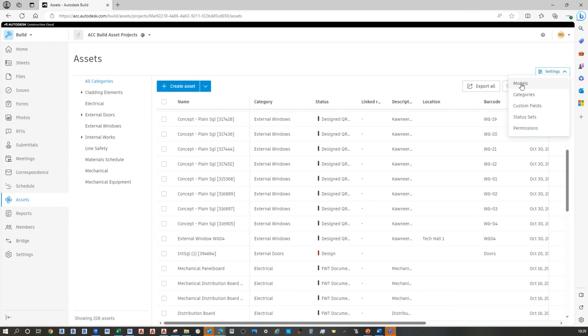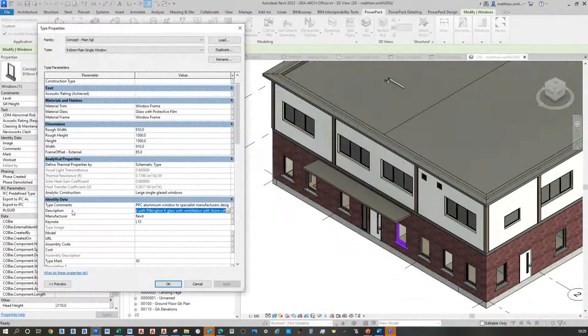We want to clearly define what the 3D model is that we are using. Now, obviously, this would be identified potentially within the Exchange Information Requirements document or the BIM execution plan, stating that we should be either using IFCs, NWCs, or RVTs. From there, the other key thing that we want to make sure is that we identify the key parameters where the information can be found.